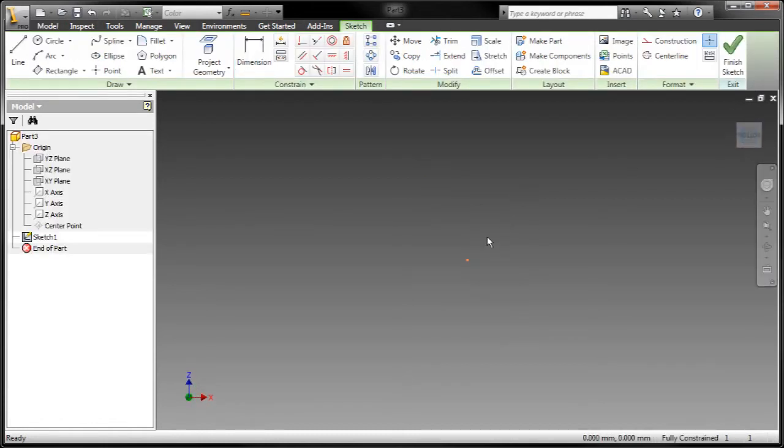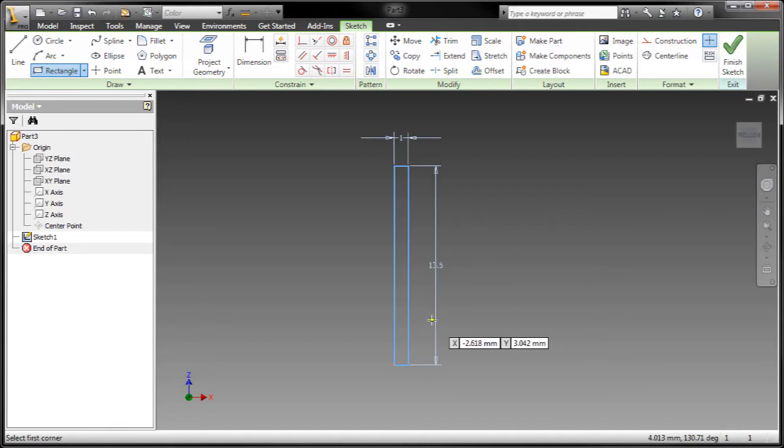Now, the first thing we're going to talk about is the dynamic input for sketching. Essentially, what we've done here is we've taken the familiar AutoCAD sketching environment and put it right into Inventor. Now, with Inventor 2011, dynamic input in the sketch environment provides a heads-up display to help you keep focus in the sketching area. So when dynamic input is on, the value input fields near the cursor display information that is dynamically updated as the cursor moves.